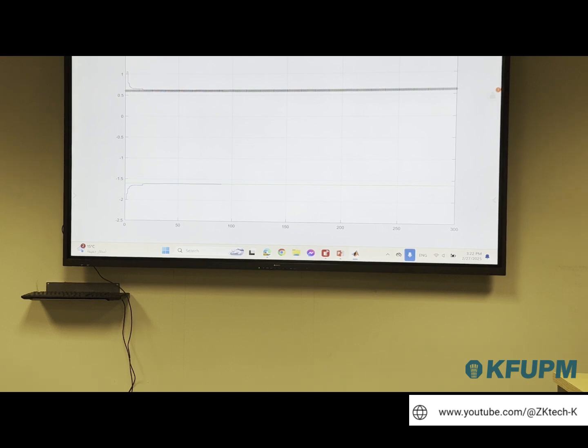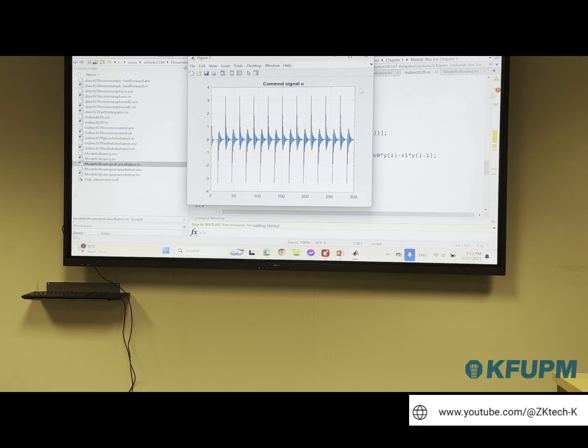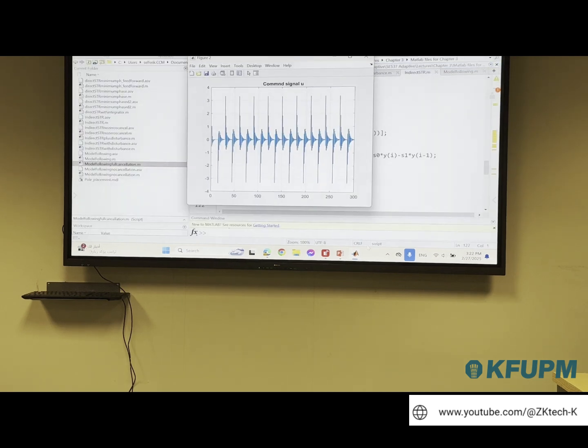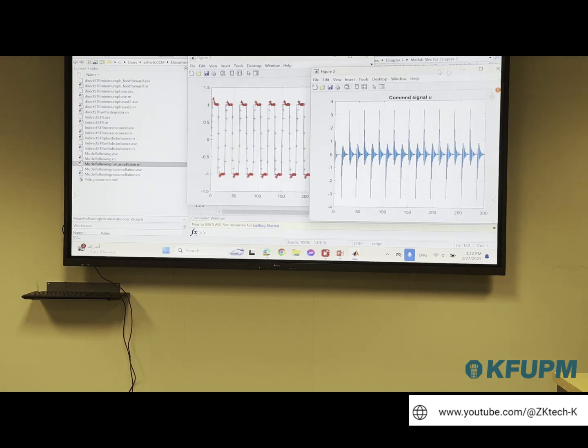Yes. So during this transient of the estimation of my parameters, the A and B that I'm using are not the correct ones. They are still in transient. This is the control signal. The control signal is like this because I'm using a step change as an input. So in fact, maybe I should start with the step before I go to the control, because by itself, the control is very significant for me. This is the output. So I put a stair step. The green one is my reference model.